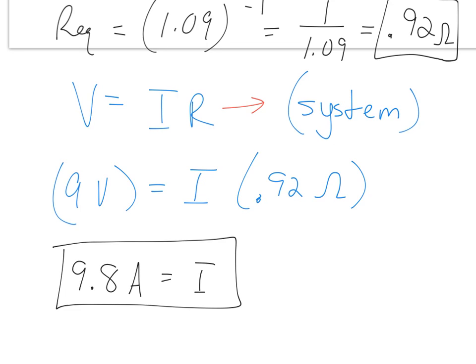What was the current in series? Scroll back up. When you did this problem in series two days ago, what was the current? 0.5. So in series, you got high resistance but low current. In parallel, you got low resistance but a higher current. You all see what I'm saying here? So again, depending upon the scenario and the application, things can vary. Your arrangements should vary as a result.